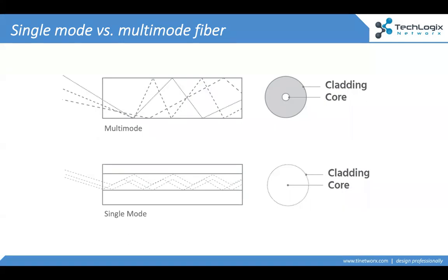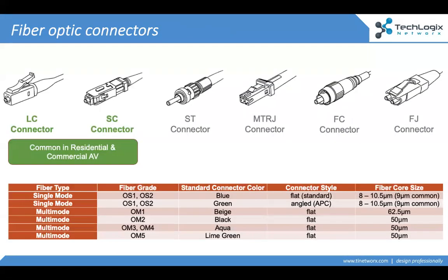So with that said, if we are using our fiber, we have to understand what kind of connectors we are putting on it. Over the years, there have been a lot of different fiber optic connectors. The good news is there are really only two that are widely used in modern projects and modern electronics, LC and SC style connectors. If you do go into a retrofit and find barrel connectors like the ST or FC, for example, those are predominantly the ones you'll see in older projects. If it's not an LC or an SC, you can adapt them.